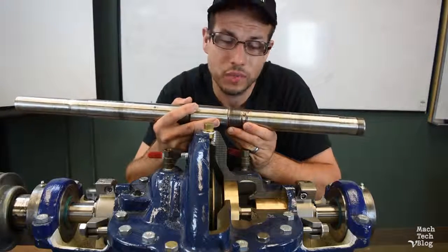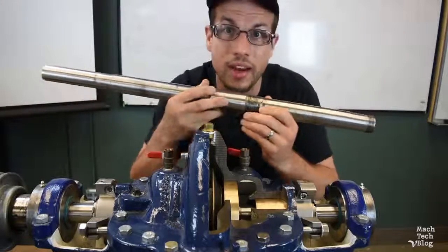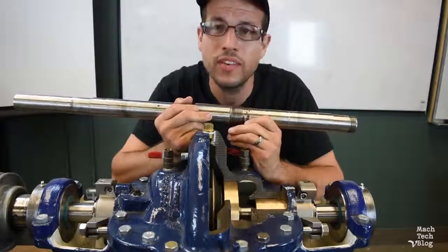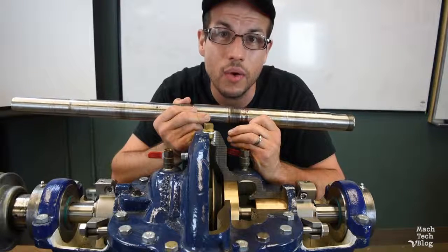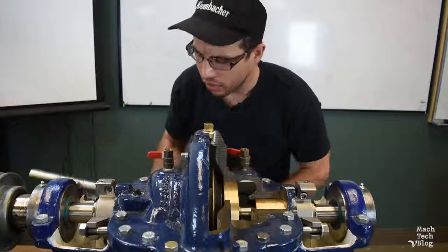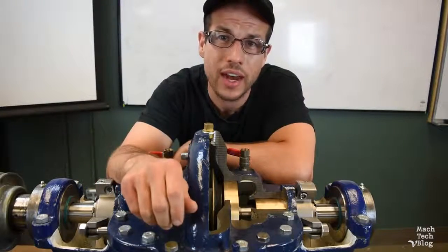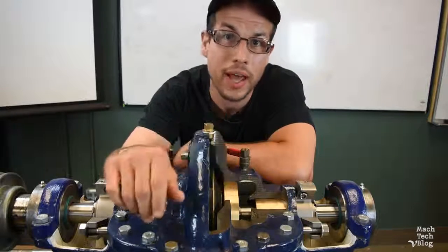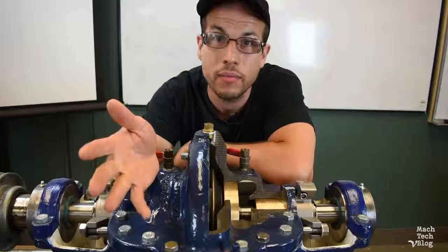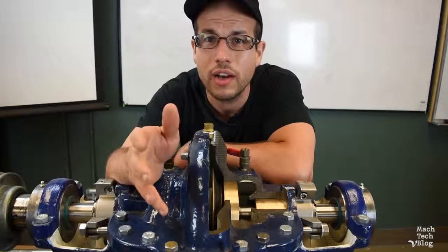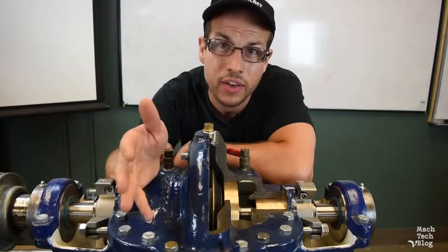Secondly, this shaft is essentially free to flop around inside of the casing or even shoot out the backside if it wants to. We need some way to restrict the motion of the shaft inside of the casing and locate it. And the third thing is that the shaft has many forces acting on it, whether it's from hydraulic imbalance in the impeller, a bent shaft, or mass imbalance, whatever it is, we need some way to support that load.